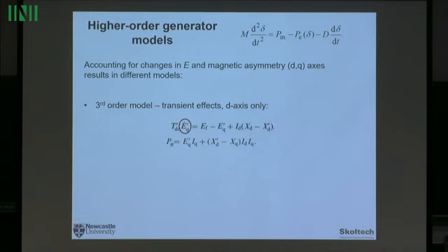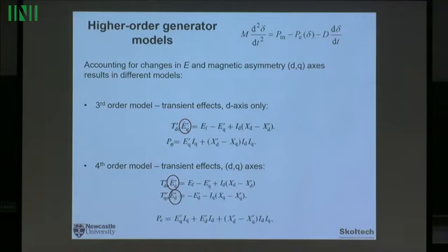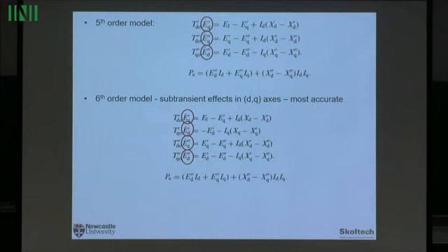And John asked me at one point the question because he was interested in the dynamic phenomena. So basically, third order model is the simplest approximation which you can take if you want to model changes in the voltages, which is one additional differential equation. If you go down, you increase the accuracy of modeling, but it may not always be necessary.